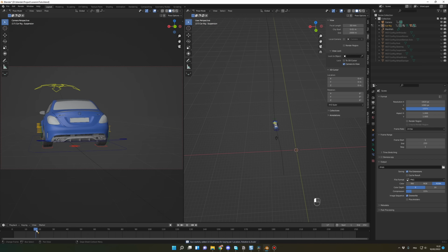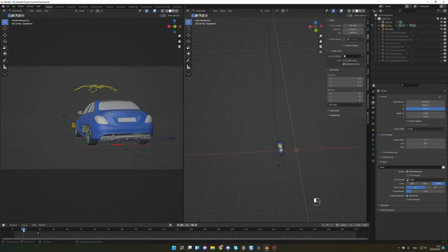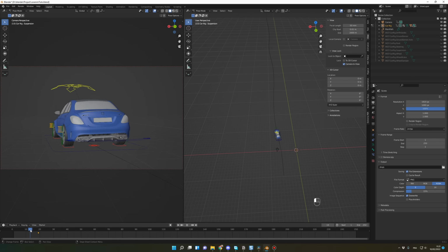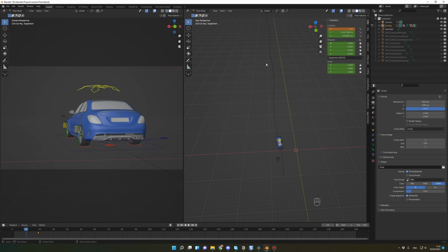But now, your car is always in this position. So you have to start the animation at a point. So maybe we could start the animation at the beginning of the curve. So maybe here. So here, you click on the control again, on item, and you put the X to 0. So it's going back to the original position. And now you press I again.